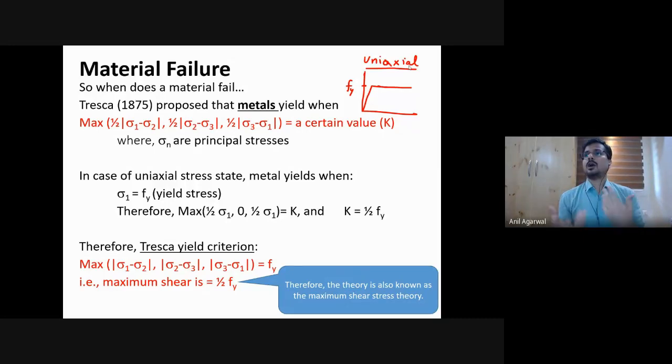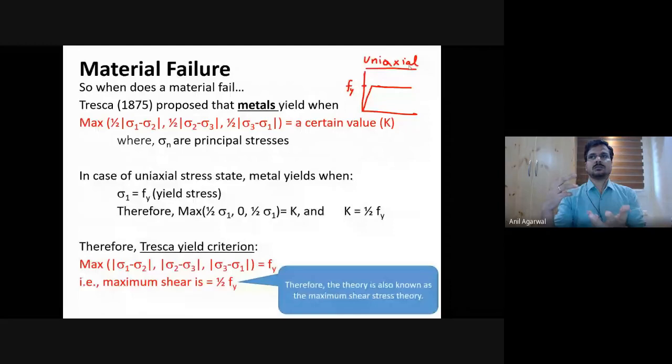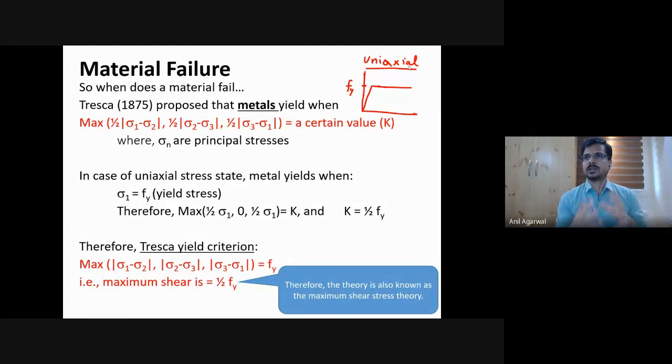or some other kind of a problem, then how do I define when the yielding will happen? Because then the stress is not uniaxial, when it is more complex, right? So I may have sigma xx, sigma xy, sigma yy, sigma xz, sigma yz, sigma zz. All these components will be present, like 6 unique stresses. Okay, so they are all present, and from there, how do I know when the yielding takes place? Because it will take place when a combination of them reaches a particular value.